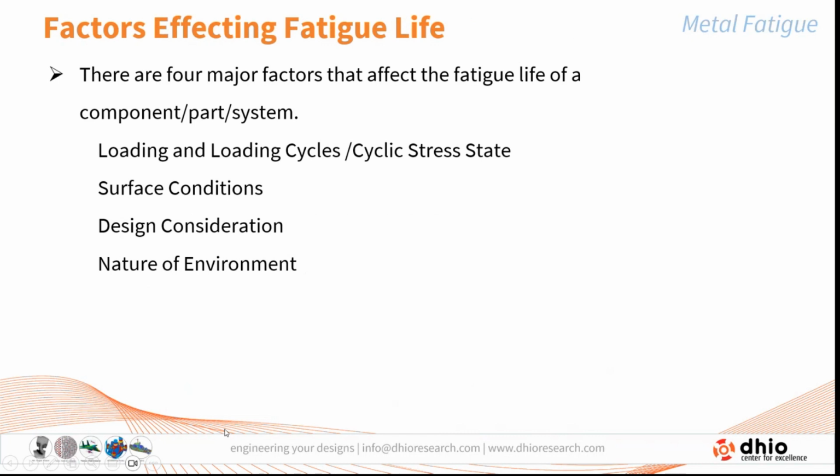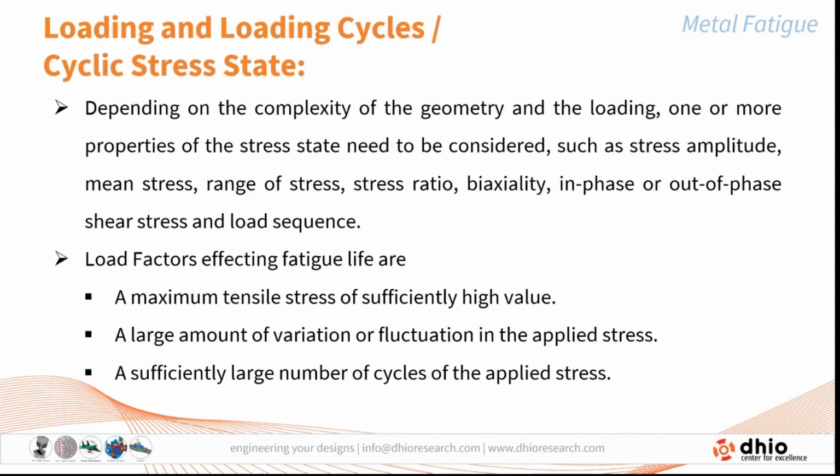Now, there are four major factors that affect the fatigue life of a component or a part. Those are the loading and the loading cycle, or the cyclic stress state. The second is the surface condition. The third one is the design consideration. And then the natural environment, which causes the fatigue life to deteriorate.